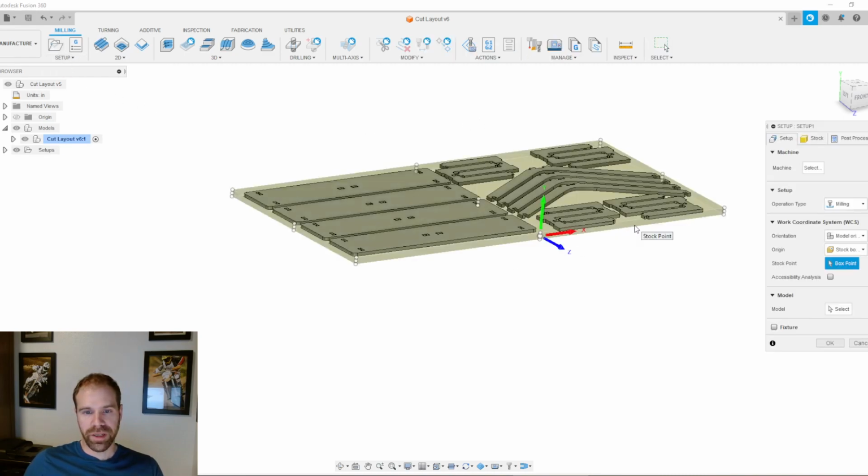So the very first thing is you need to know the axis coordinate system of your machine. This is super critical. Most routers that I know of have the z-axis as the spindle, and then I'm going to actually think here for a minute. I believe positive x is the 4-foot direction and positive y is the 8-foot direction. So what I like to do is I'm going to show you this first.